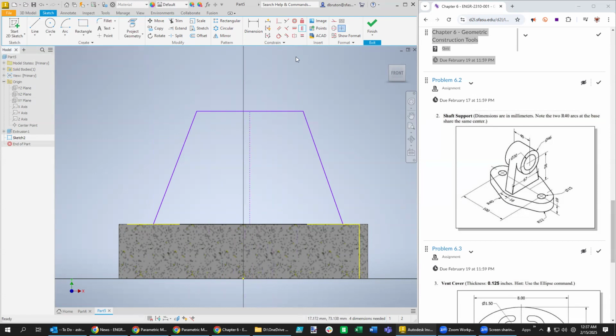I think what we want to do is actually select points. So on this tool, we select this point and that point. And you see it shifted it over now. So now we have something that's a good reference point for our y-axis. It's better to do these as hidden lines, in my opinion, because if you decide to move this part away from the origin, you can do so by removing the constraints on this part.